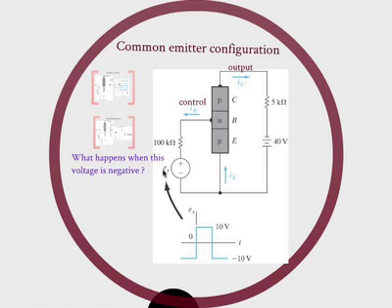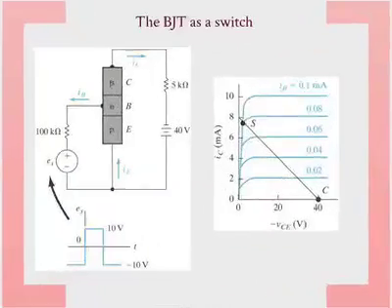Okay, that's okay. So let's look at the opposite situation. When this is positive, of course, analogously, it should be reverse biased. Now, what does that mean when my base emitter junction is reverse biased? No injection. So what happens to the collector current? Yeah, basically be 0. Or very low. Okay, that's my switch. Right? I'm just going from forward bias to reverse bias, and that's my switch. Simple. Okay? I can actually stop there, I guess.